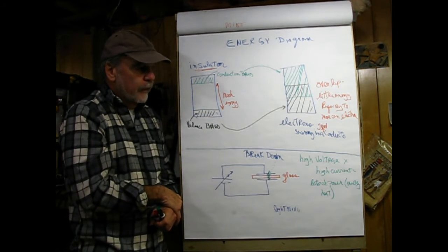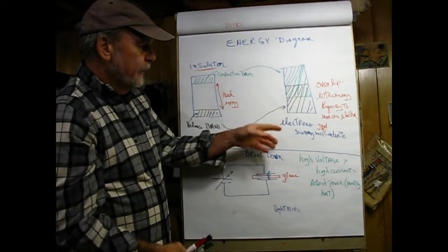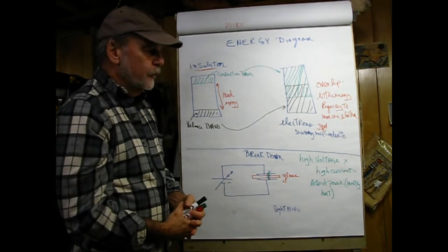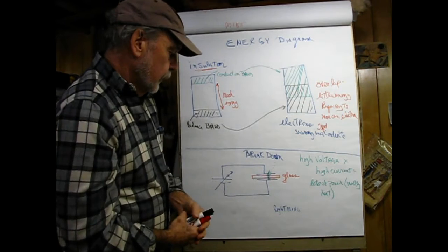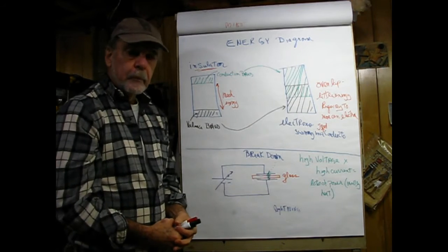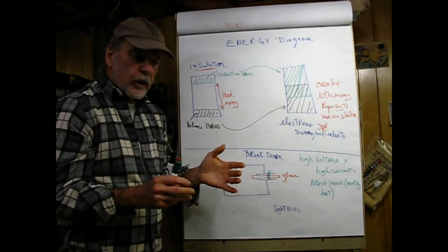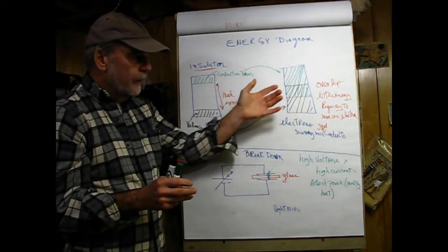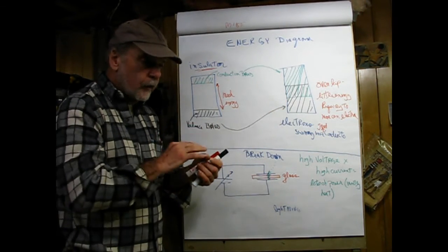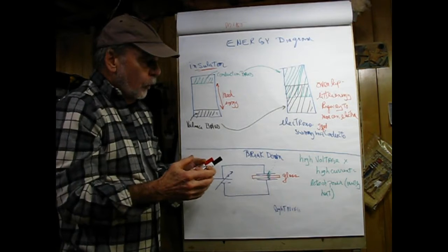On the other hand, for a conductor like copper or silver, which is considered to be the best conductor, the valence band and conduction band overlap. So it takes very little energy to free up an electron. Now, let's consider silver for a minute in a mirror. If we look at a mirror, what we see is an image in it, and it's shiny. The reason that's shiny is that in silver, these electrons are so loosely bound that the very heat of the room causes them to be in the conduction band and able to move. So that's why it's shiny.